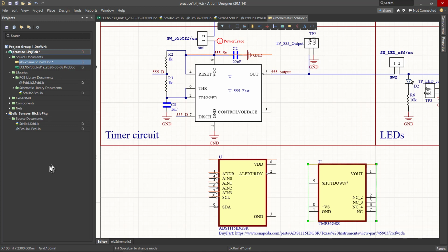But in the short term, before I build that integrated library update, I can use them immediately by using the local library package in my PCB project. And now those symbols and footprints that I've brought in are available to do something with in my circuit. So the last step is we need to go in and we need to clean up the symbol and the footprint a little bit in order to make them a little bit more robust for our application.